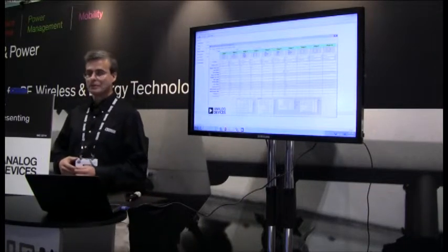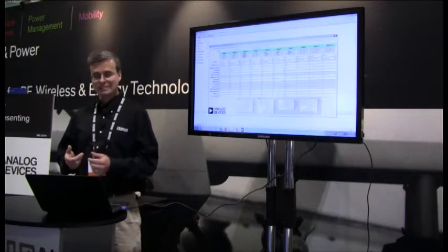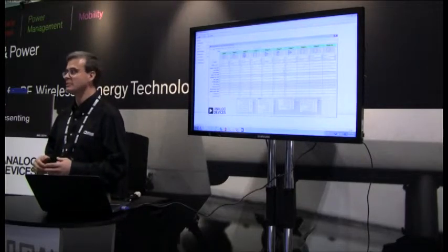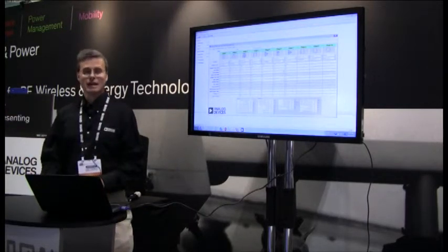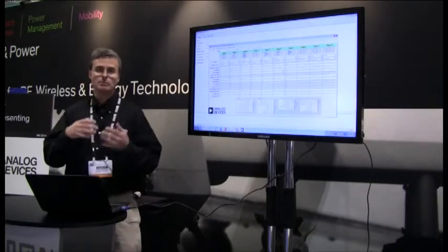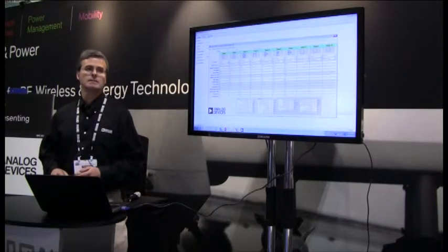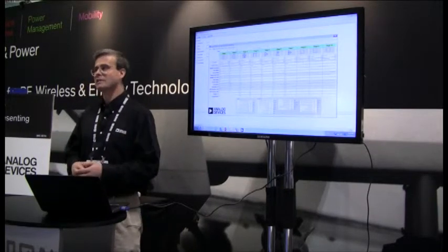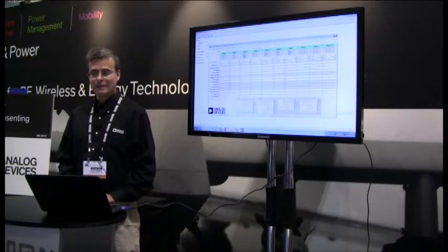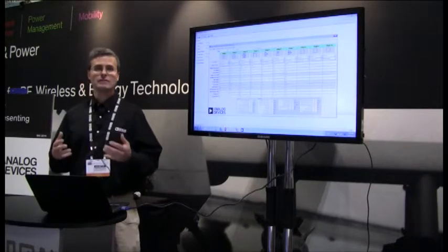This gives you the ability to calculate noise figure, cascaded noise figure, output power. It gives you the ability to say, hey, I'm putting too much power into this amplifier, so you'd be able to put a pad before it to adjust that power. It gives you all the flexibility to do an initial simple signal chain calculation, making it very simple for you.